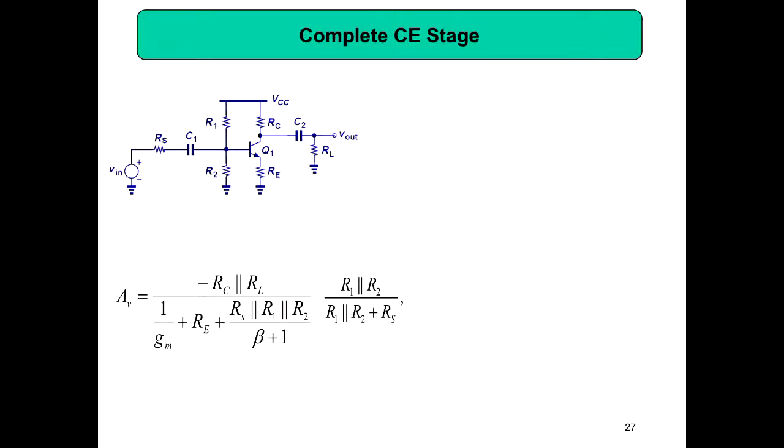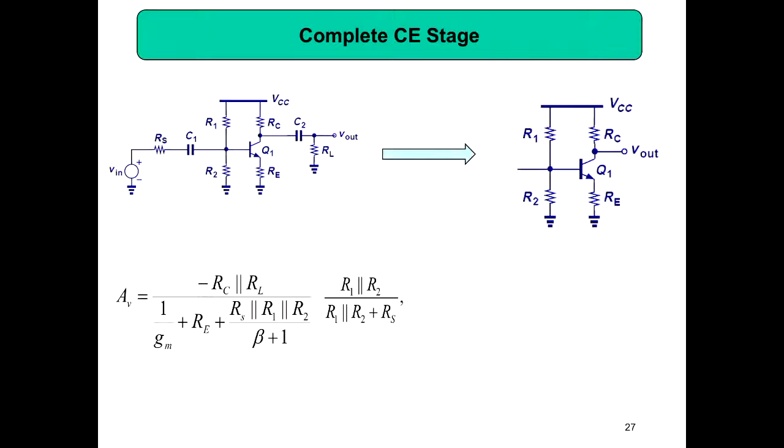So this is the expression. Then my question is how to find the voltage gain for this one from this expression, because we know this is the voltage gain for this big circuit, and then for this one what happens? For this one, we don't have Vin. You don't have to take Vin into account because anyway Vin is not here. Then what is the RS for this circuit? Then you can put RS equal to 0 here.